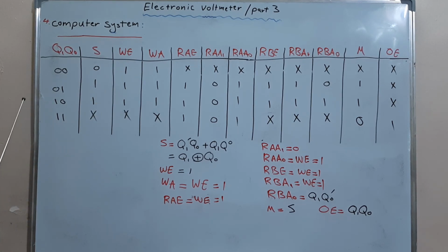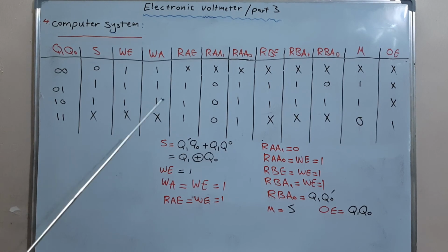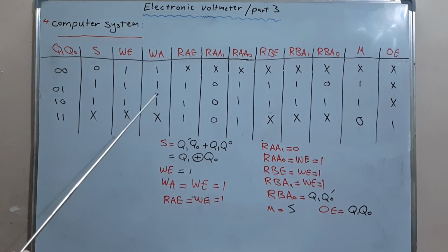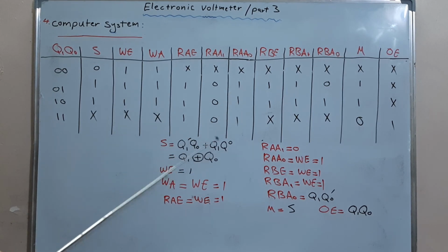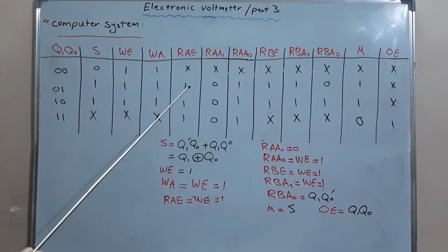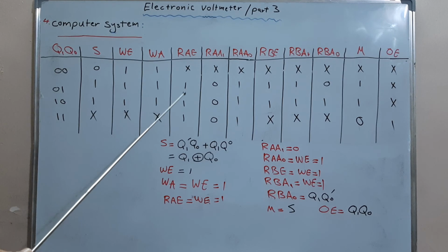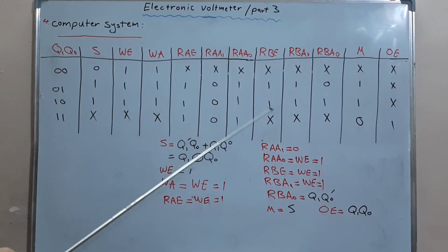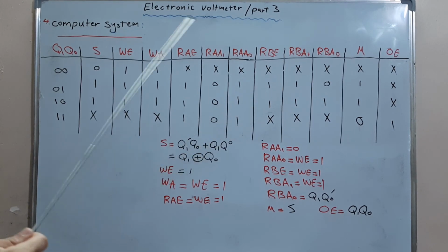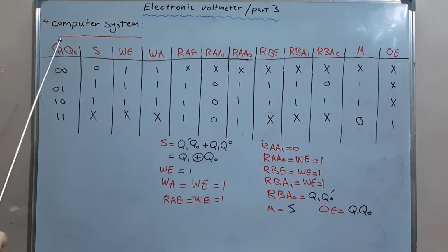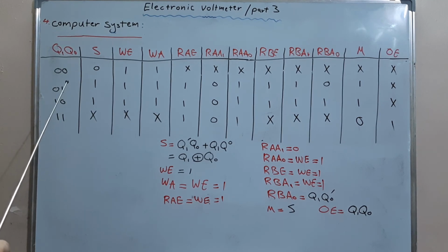In the second state, the decoders of reading are both enabled, and the values in both the second and the third location will be read by port A and B respectively, multiplied by each other, returned back to the multiplexer, and by putting S equal to 1, it will pass to the register file.